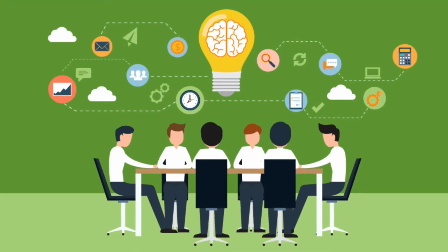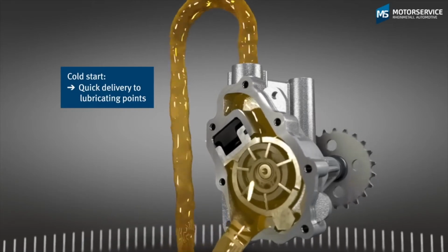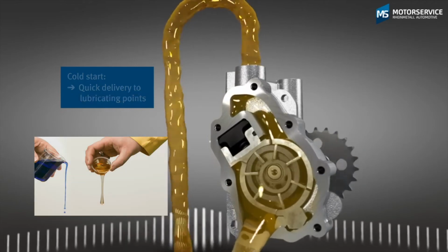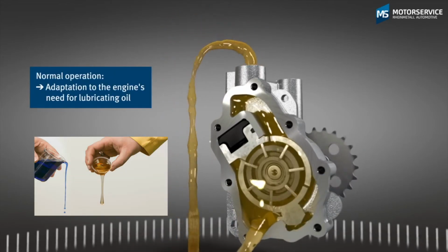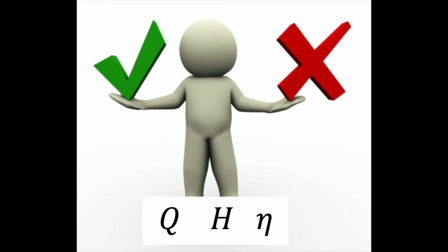To develop this project, it was necessary to know about the operation of pumps with viscous fluids. When a centrifugal pump is used to pump high viscosity fluids, its behavior changes dramatically. This is due to the losses that occur inside the pump. When this happens, the performance of the pump is estimated with some correction factors for the flow, head and efficiency, according to the Hydraulic Institute.